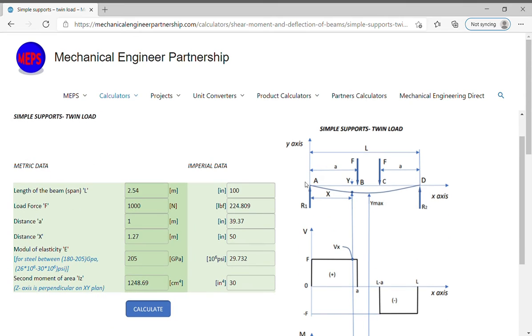The figure shows a beam simply supported by reactions R1 and R2 and loaded by two F forces located at a distance from the ends of the beam. If the beam is cut at some section located at x and the left-hand portion is removed as a free body, an internal shear force V and bending moment M must act on the cut surface to ensure equilibrium. The shear force is obtained by summing the forces on the isolated section. The bending moment is the sum of the moments of the forces to the left of the section taken about an axis through the isolated section.